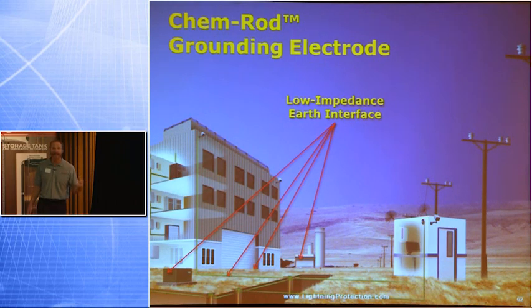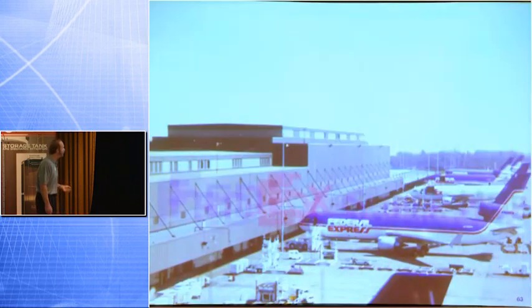And most times it's very easy to get, especially with the chem rods. Now in Louisiana, not much, if you're down in New Orleans or Lafayette, you just dig a hole, you get a good ground. So obviously it depends on your location. West Texas, Dallas, you got a problem with ground. Beaumont, Houston area, the Beaumont Ship Channel area, not too bad because your soil is so conductive. And we'll talk about that later on too.